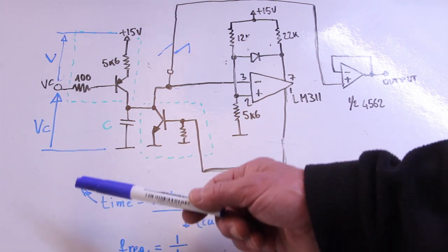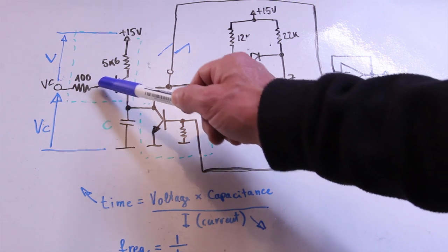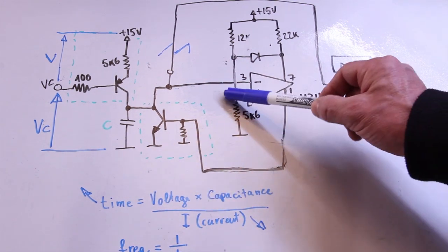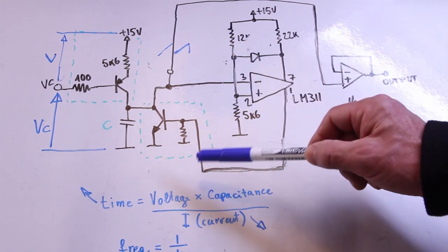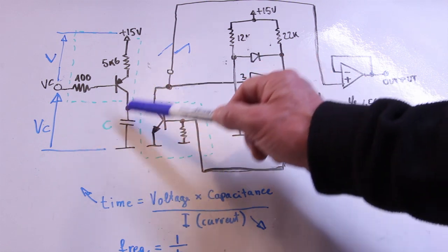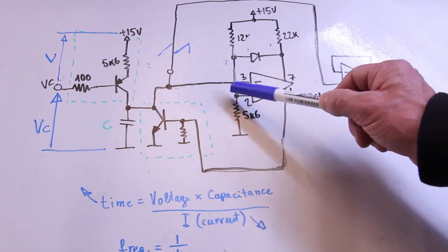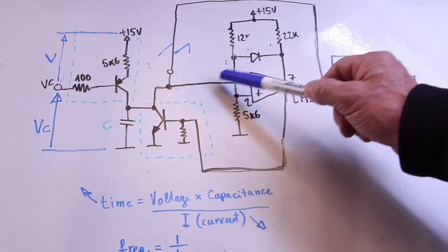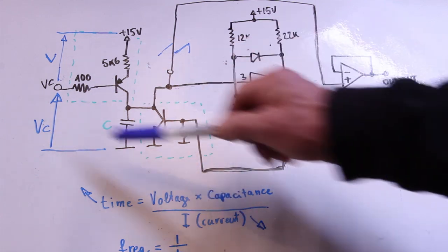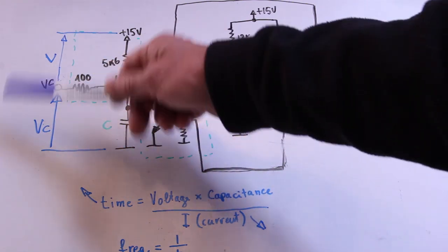is the lowest frequency. And furthermore, if this voltage goes below this point, the voltage divider here of the comparator, this capacitor won't be able to charge to reach that voltage, and so it won't be able to reach the threshold voltage, stopping the oscillator altogether. So we have to do something to correct this.